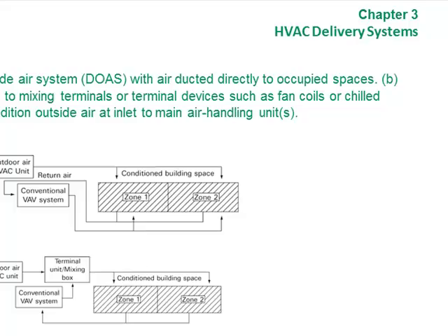But how about 3.17? Why would you recommend the extra construction cost as the architect? Why would you recommend that for a four pipe fan coil system versus a two pipe fan coil system? Because overall, in the long run, it would reduce energy costs by running the AC system in shorter time frames than longer time frames.